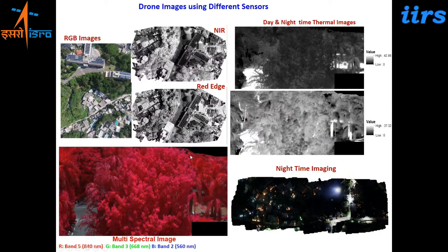So in this case, there was a geological fault also, which was not seen on the original data sets, but once this information like the height information was extracted, and then we derived the bare earth model, so we could see the geological feature also very clearly from this data sets. So this is the bare earth model. This elevation model is this one where height of the features is also there. Minus the height of the feature, one can generate the bare earth model.